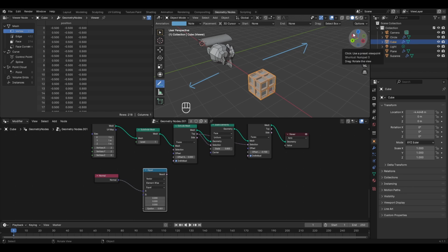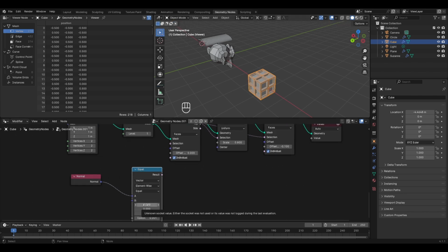Similarly, you also have other axes like the x-axis and the z-axis. So in case of x-axis, this one is positive and this one is negative. Now I'll remove all this by pressing Ctrl plus Z 6 to 7 times and click on the select mode again. To see the extrusion effect applied only on these faces, I'll go to the value B, and here you can see that this one controls the x-axis, the second one will control the y-axis, and the last one will control the z-axis.